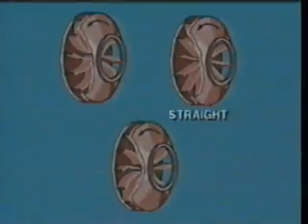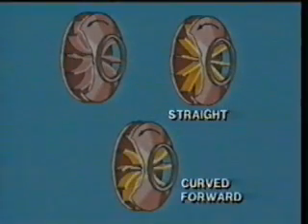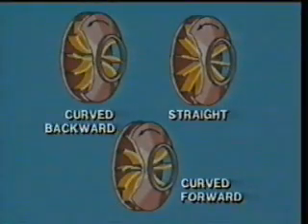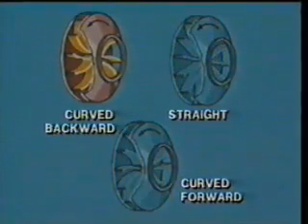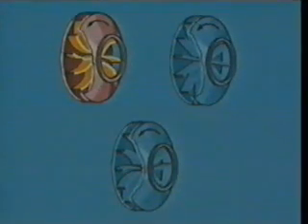The blades, or vanes, on an impeller can be straight, curved forward, or curved backward. Backward curved vanes are the most efficient and stable. However, since backward curved vanes cause the gas to leave the impeller with less velocity, there is less velocity to convert to pressure. Most oil-field centrifugal compressors use the backward curved vane impeller.